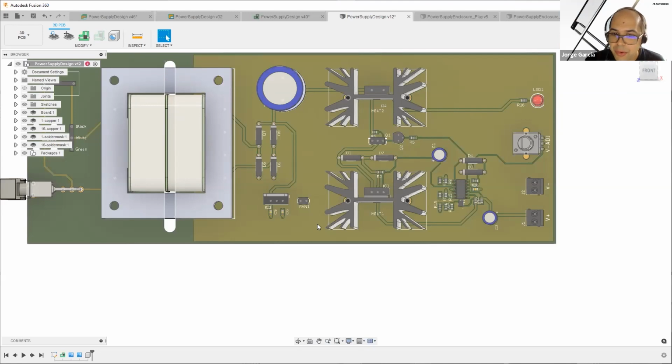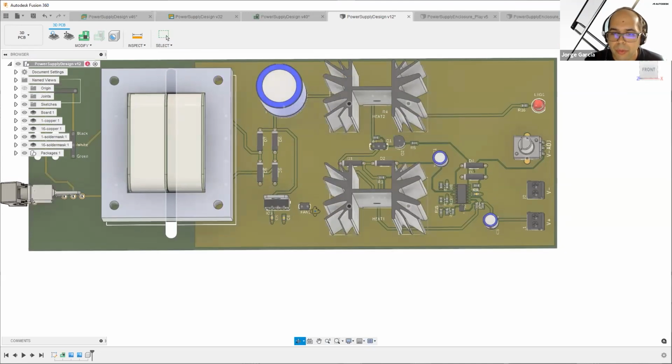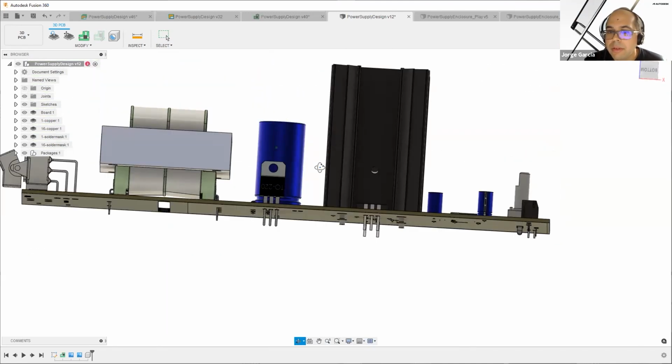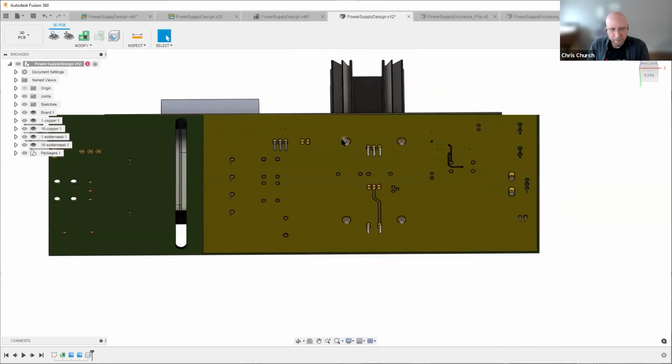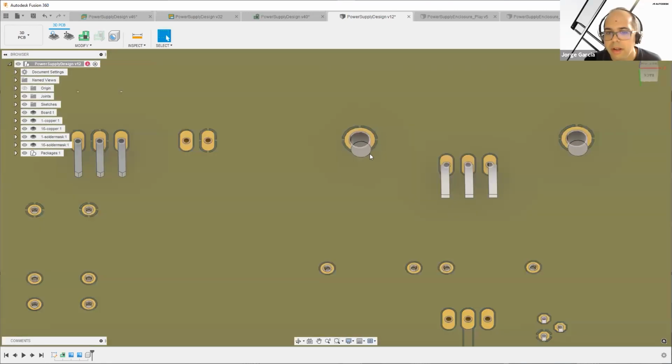So as designed right now, when I bought these heat sinks, they actually have these little nubs, and those little nubs solder into the PCB. Okay. So if you look, they have some thermal relief. Right. They're set up to solder to ground. While they do have thermal relief on the pad, let's remember these are heat sinks, right? And their job is to transmit heat away.